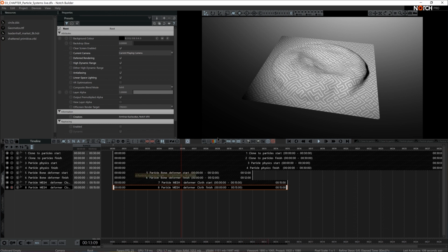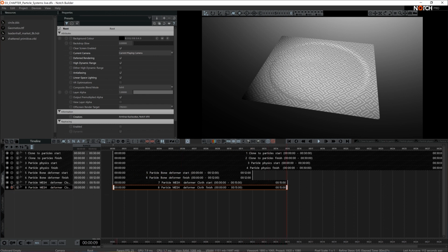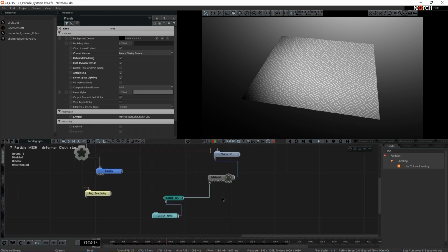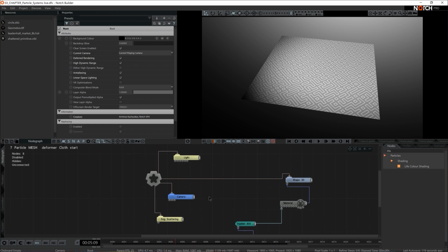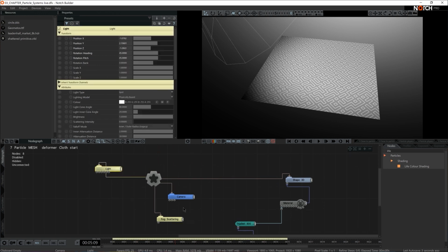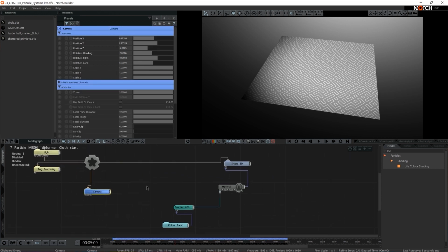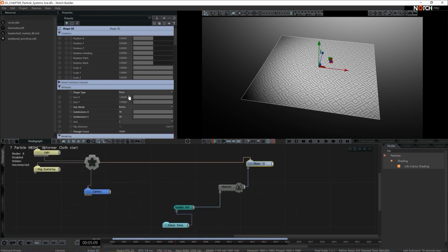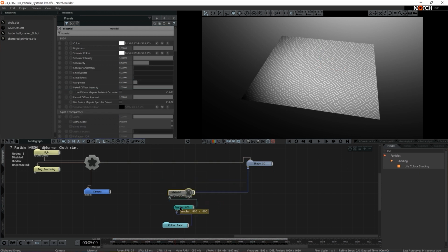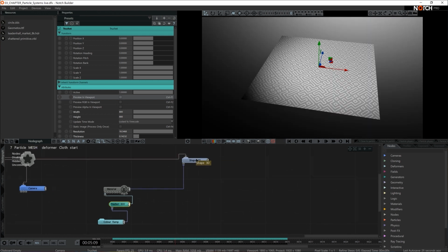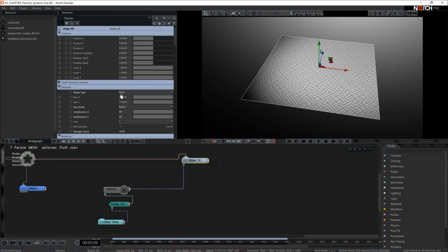So here is a finished setup and we have these starting points. So I think we can easily just go ahead, open the layer 7 and talk about the nodes available for us here. So we have a couple of nodes working with lighting. So that's a light and a fog scattering. We have a camera that we're looking through now. And we have this shape 3D, which is set to a plane. It has a material, and this material is built with a Truchet generator. And here we have a shape 3D set to a plane, and we're going to use it for mesh deformer.